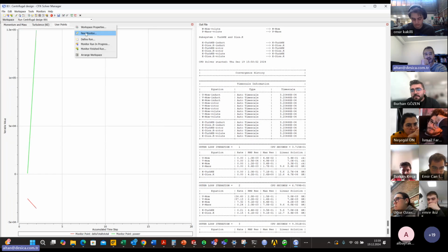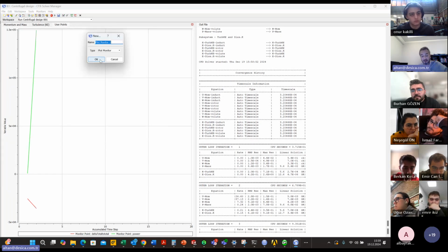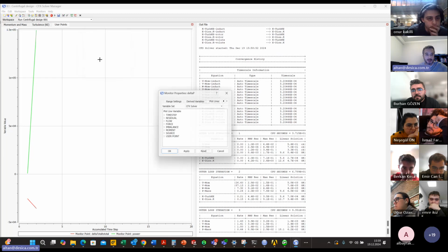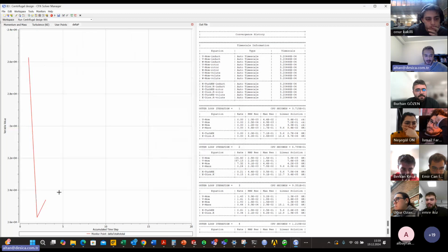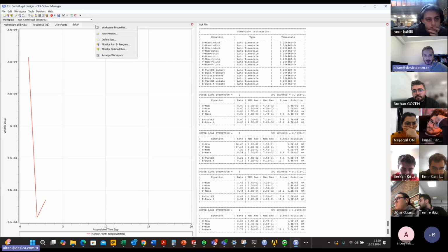You can right click here and click new monitor, delta P. We can monitor delta pressure during the solution.